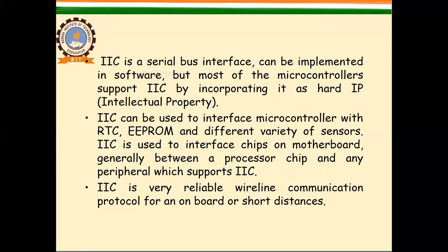So if 2 or 3 microcontrollers are connected in the system and all of them want to communicate with the memory, either to store or to receive data from the memory, then SPI can't do it. You need another protocol. And then there comes I2C, because I2C supports a multi-master and multi-slave system.